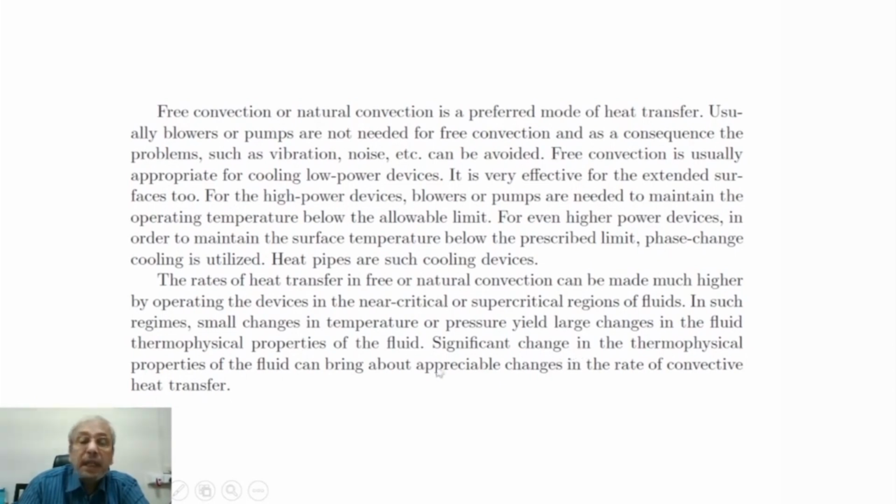Significant change in the thermophysical properties of the fluid can bring about appreciable change in the rate of convective heat transfer. So free convection is a very important process, and many times we can gainfully utilize this for cooling of electronic equipment and cooling of computers which are not very high power or power intensive computers.